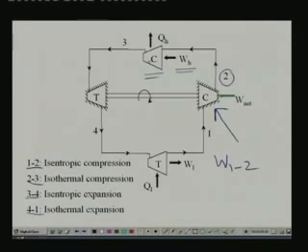Since its temperature has to remain constant, obviously there must be some heat transfer, and if you are applying the steady flow energy equation, you can easily show that the work input should be the same as the heat transfer rate, so that your temperature remains constant for the ideal gas.